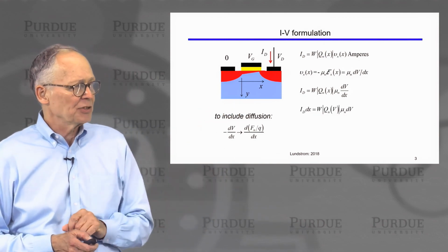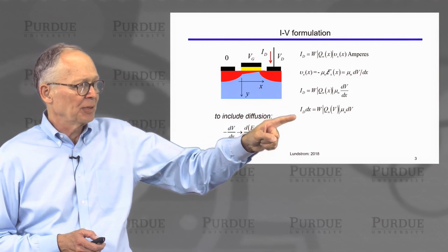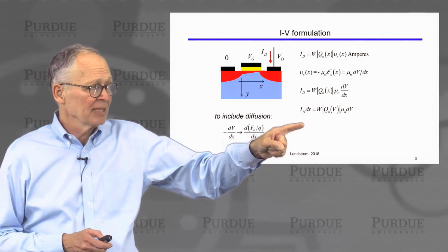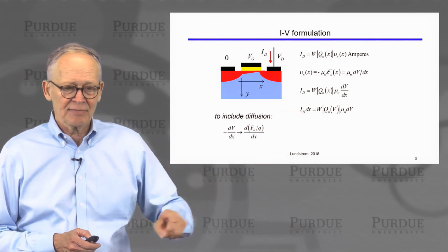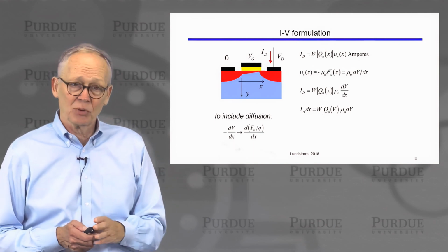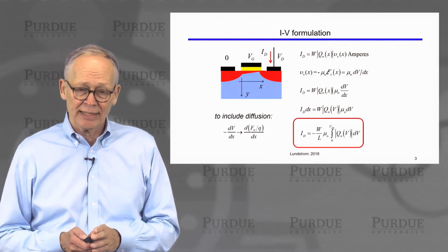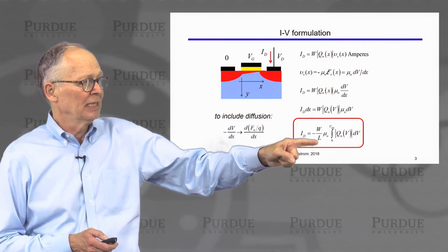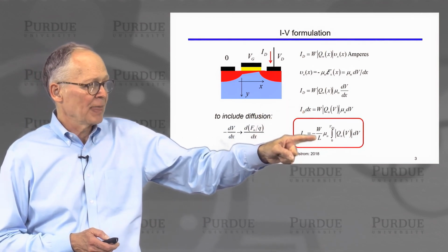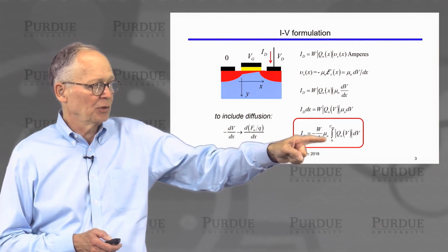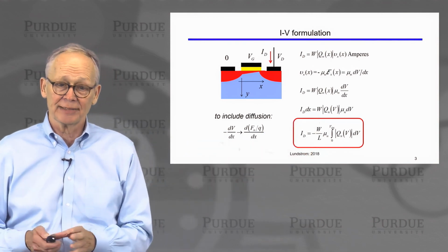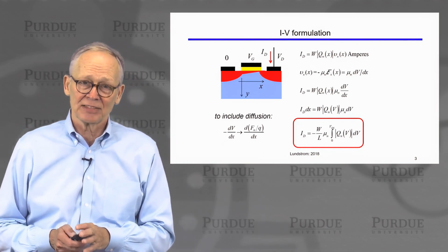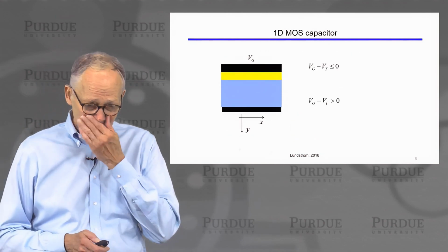All right, so we have an expression for the drain current. We can separate variables. We have the current is constant along the channel. So we have I dx. And then we have a function of voltage on the right-hand side. We can integrate both sides. We'll integrate the left-hand side from 0 to L. So that's bringing in a 1 over L here. And we're integrating voltage from the source voltage, which is 0, to the drain voltage, which is Vd. So now we've got an expression. All we need to do is to specify charge as a function of voltage in the channel.